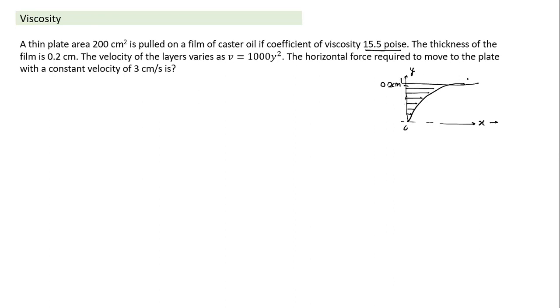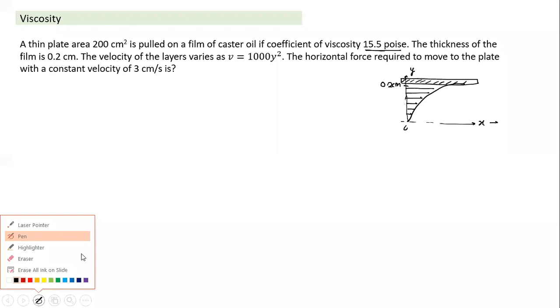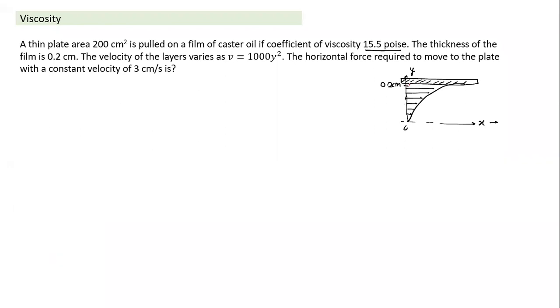So this thin plate is in contact with our next layer of liquid, and between this thin plate and the liquid, shear force will act. Which is the liquid layer? This is the liquid layer. And what is the force? Viscous force will act at this level. This viscous force will depend on the velocity gradient at y equal to 0.2.